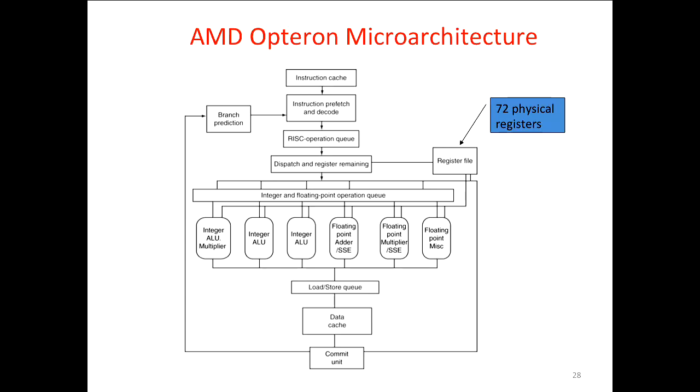And what's more exciting is they can do those out of order. So you're reading the program in one order from the instruction cache. You're figuring out on the fly how to reorder those, breaking them into micro-ops, and figuring out on the fly how to reorder those micro-ops to try and keep everything busy. And all this is being done in hardware on the fly inside the machine. That's happening in here. And what's more, it's doing this thing called register renaming, where you think you're writing register 3, but in fact the machine is writing to some other register. You could have multiple instructions that all think they're writing to register 3. They're actually writing to different places inside the machine.